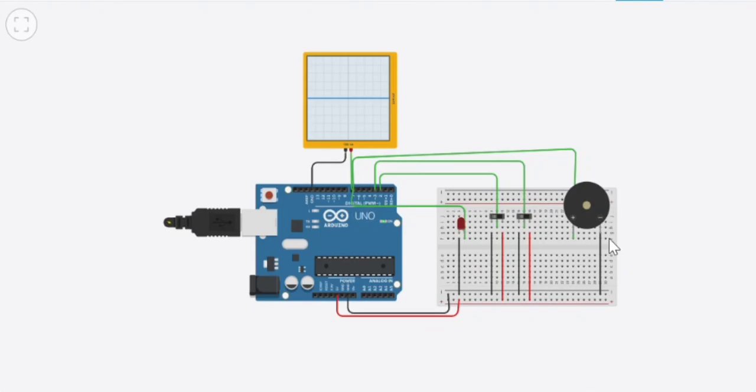Now let me conclude this project. This project is a seatbelt occupation warning system aimed at improving vehicle safety using Arduino UNO. It uses two slide switches to simulate a person occupying the seat and the seat belt being worn. Based on the logic, if someone sits and doesn't wear the seatbelt, a buzzer sounds with an LED after a short delay. If the seat is empty or the belt is worn, no alarm triggers. This project is practical, lightweight, and simulates real-world car safety systems using simple hardware. It teaches how embedded systems use sensors, interrupts, and PWM to control outputs based on logical conditions.